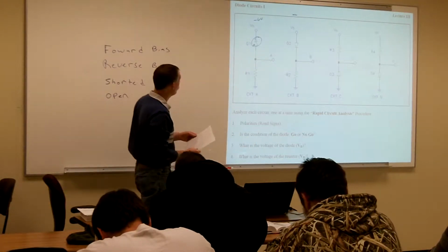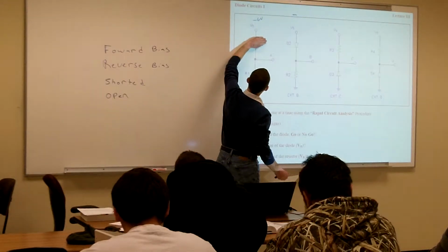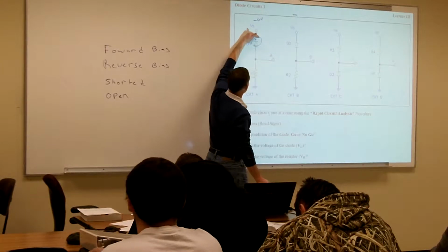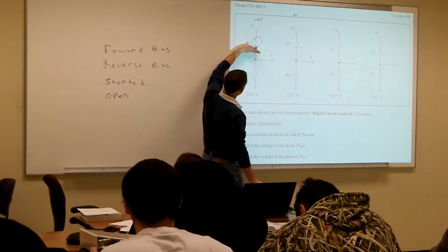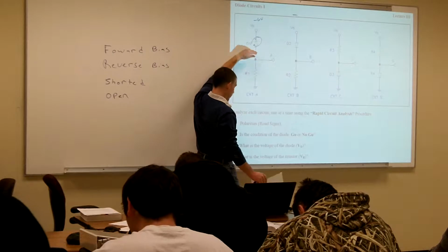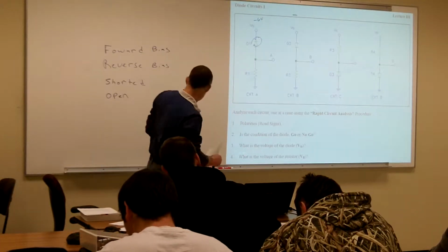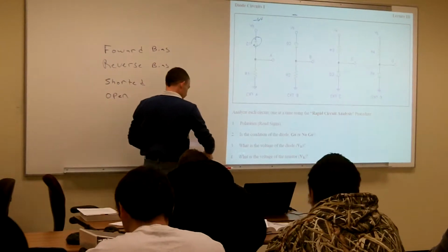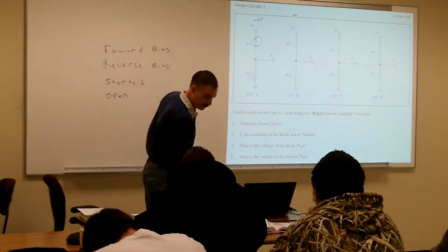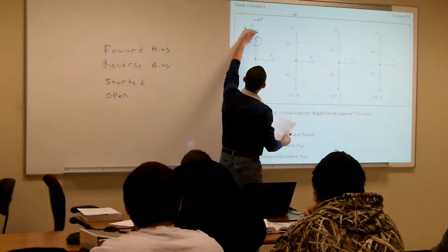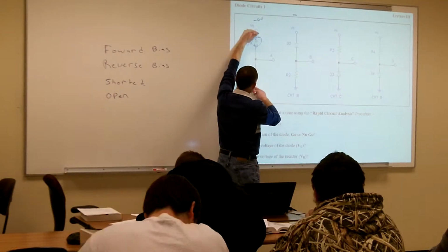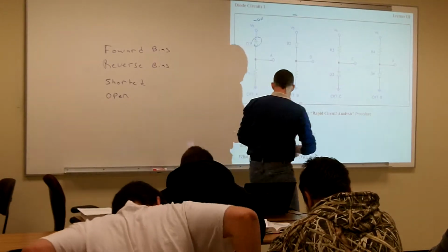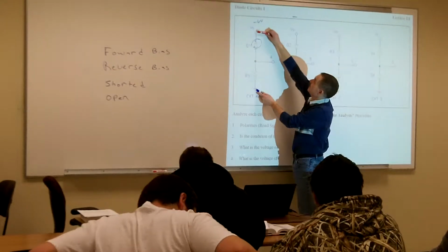Yeah, treat that diode as an open. Then we're going to do it like we're doing test point measurements. We're going to measure what the voltage would be on the cathode side and on the anode side. The word I was trying to think of on Monday is that we call these soft voltages. When we treat that diode as an open, these are just to analyze the diode itself.